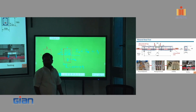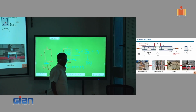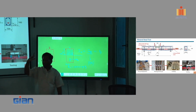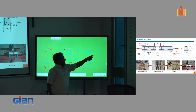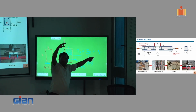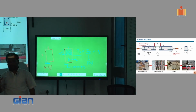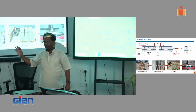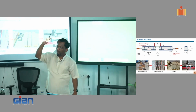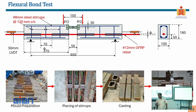I gross, right? Now this I effective should be a function of the moment at which you are doing the calculations. So if my moment is very close to the cracking moment, I effective will be close to that of IG. If it is much higher than your cracking moment, it will be getting close to that of the cracked moment of inertia, right? So that's what it is. You have to do the calculation. So I effective is a function of the moment at which you are doing the calculations, right? Okay, you got the point?